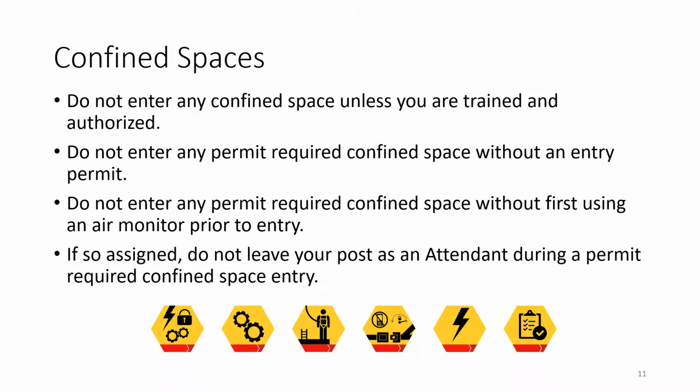Confined spaces. Do not enter any confined spaces unless you are trained and authorized. Do not enter any permit required confined space without an entry permit. Do not enter a permit required confined space without first using an air monitor prior to entry. If so assigned, do not leave your post as an attendant during a permit required confined space entry.